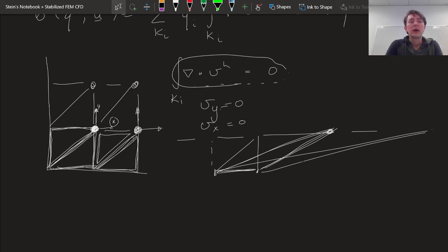And that also illustrates how sensitive these formulations are to your choice of spaces, right? Naturally what we want to have is a space that works for any kind of domain and any kind of boundary conditions, right? So we wouldn't want to use spaces that start to show these kinds of problems in particular cases. Maybe in any corner where you have 0 velocities prescribed on part of the edges of the corner, you would get locking, which might also affect the remaining volume.